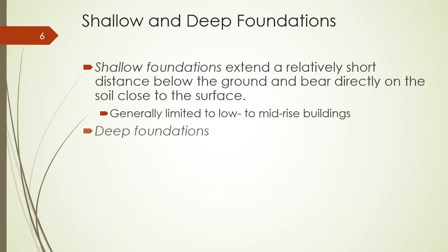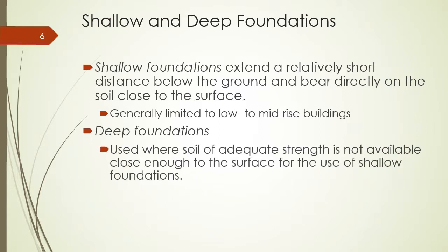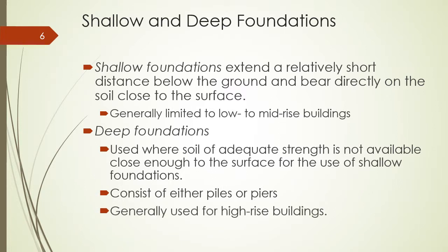The deep foundations are going to be used where I have soil of adequate strength, but it's not available close enough to the surface to allow me to use a shallow foundation. So here I'm going to be either using piles or piers, and these are generally used for high-rise buildings. Now, the choice of whether I use a shallow or a deep foundation is going to depend upon the quality of the soil closest to the surface.